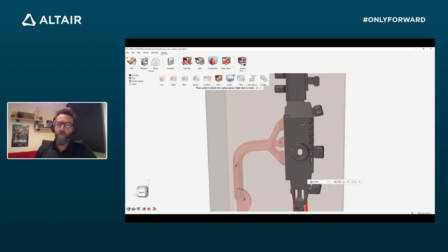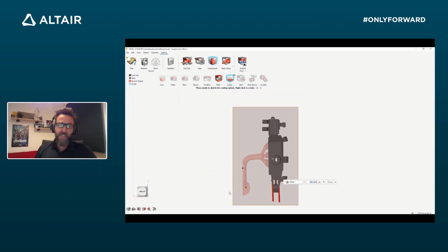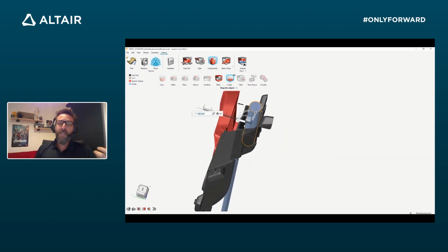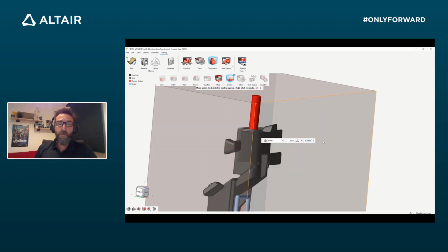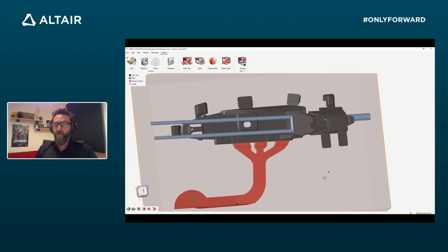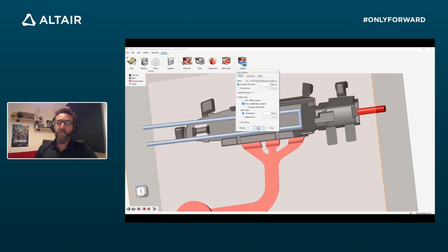We have tools to create cooling lines, move cooling lines, and modify the dimensions, coolant material, and temperature of cooling lines, and everything, as I mentioned before, is parametrically controlled. At any time, we can iterate, come back, modify a diameter, a temperature, or the size of an overflow to influence the solidification or cooling pattern.